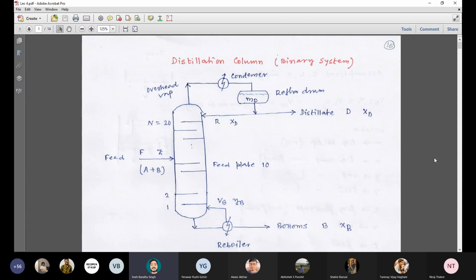For that question, I searched it, and it says saturated steam is preferred for heating applications rather than superheated. What is the reason? Because superheated steam is more like air, it has a poor heat transfer coefficient. Poor heat transfer coefficient. Okay, better answer. Anyway, you may think superheated steam has more energy, so then we should prefer superheated steam, no? Yes, sir, more energy.